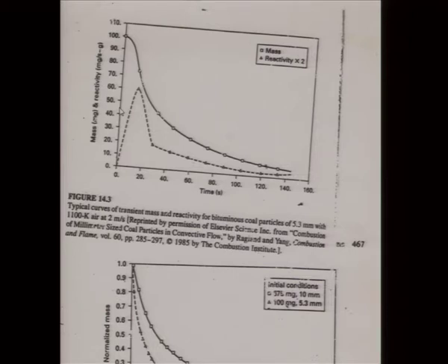So what does proximate analysis give? It gives you fixed carbon, volatile matter, ash, things like that. And what is ultimate analysis? Different elements like carbon, hydrogen, nitrogen, things like that. So the proximate analysis is done actually under some specified conditions. You take a small sample in a crucible and heat it in an oven at a particular temperature, keep it there at some temperature, things like that.